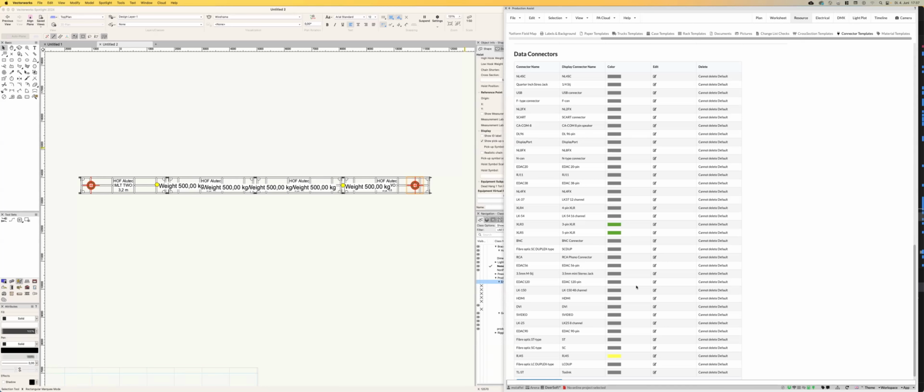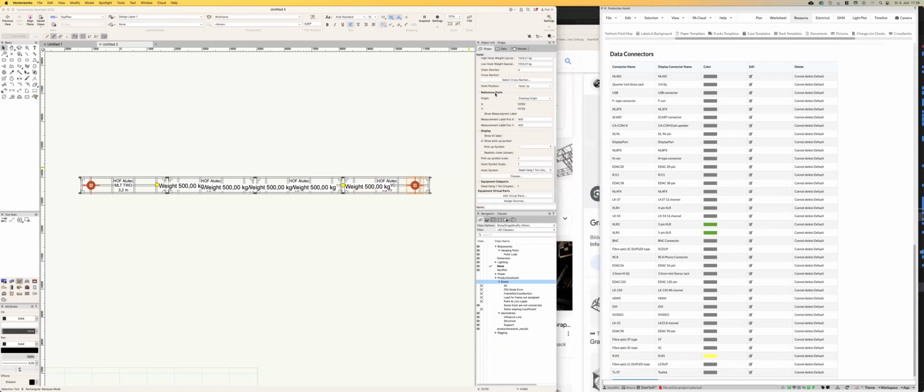Okay, that's pretty neat. Just one thing for the data tags: what type of data can be shown? Is it the same as in the motor info label field? Oh, the data tags. In the data tags, you can display any record that is in Vectorworks. It's a really nice system. It's quite complex, but it's a really good tool for documenting anything that you want. So if you want to show the hook height of this hoist, you can create a data tag for this. Okay.